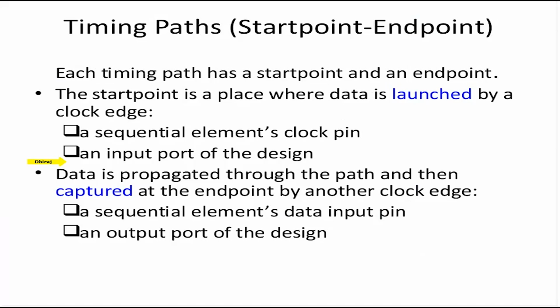Synthesis doesn't do much about hold. If we go back to the setup and hold equations, which I will deal with in much more detail in unit 5, we see that the hold timing equation does not have a clock frequency dependency.